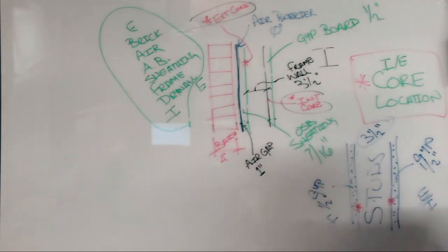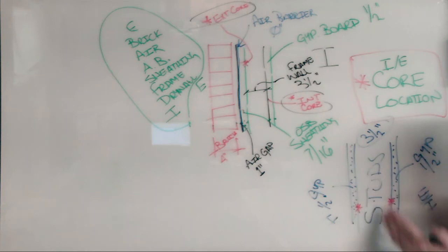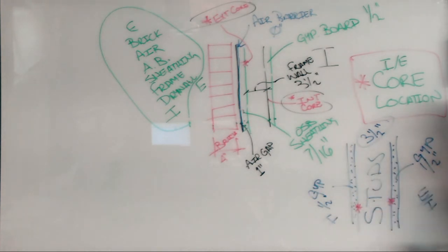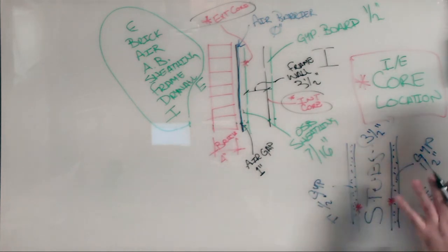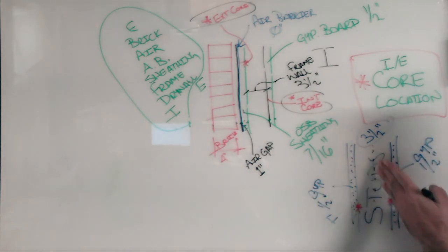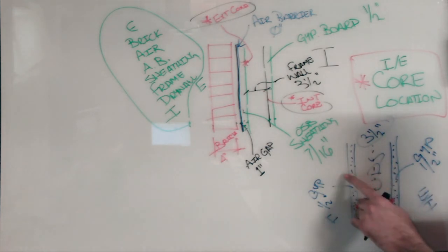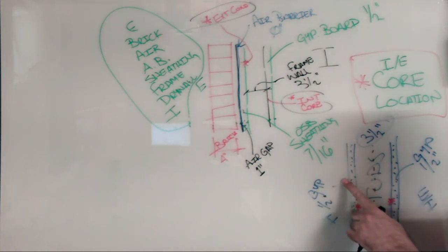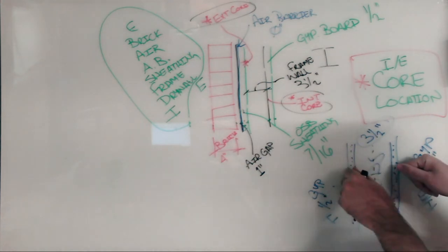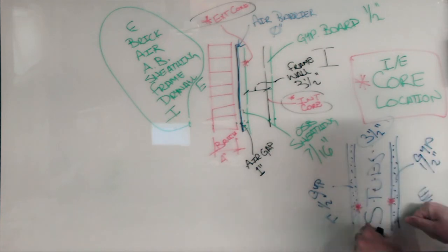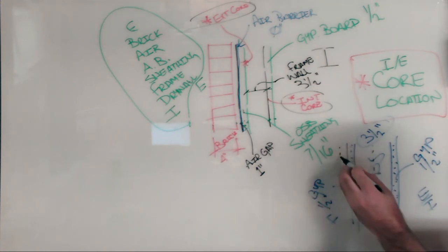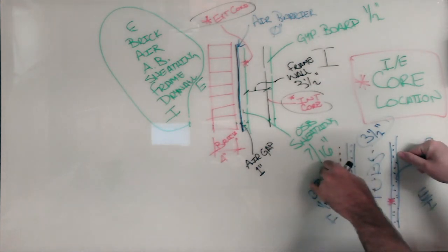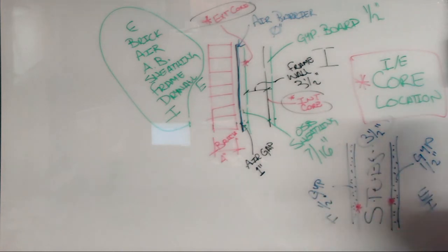Now that one becomes very handy. And we would use that in a situation like this because our core would be here, our core would be here, our center of our core would be here. And I know what you're thinking, well, isn't that the same as the exterior? Yes. In this example, what would happen if we needed a double layer of drywall on this side? Okay? But we still wanted to use the center of the stud. Because we set our cores, it's going to select the center of the stud. If we did wall center line and we had a second layer of drywall out here, it would select between these two.